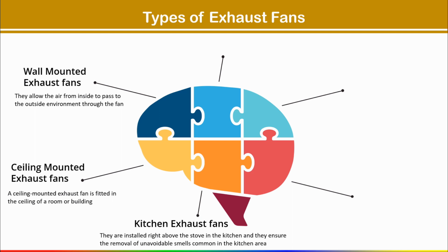Sometimes we are giving kitchen ventilation, and we know that the main purpose of kitchen ventilation is to remove the smoke. Suppose in case of fire, if there is smoke in the kitchen, we have to remove the smoke. And second, the most important is we have to save the life of people who are working in the kitchen. That is our main target. For that we are installing the hood. For hood sizing we have different methods.